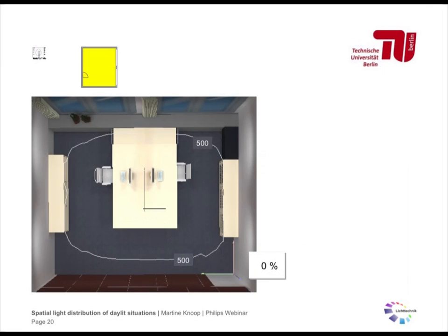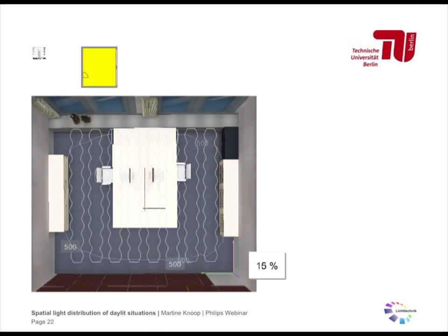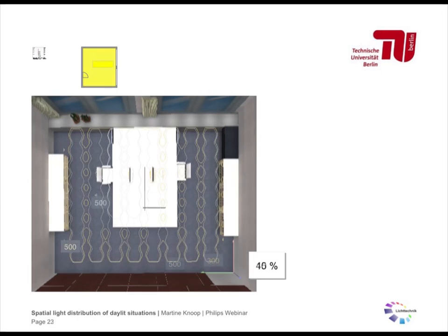Just to give you an impression about the energy savings, if I go back to the standard situation where I have 500 lux with a normal office luminaire and I realize 500 lux on average, I can of course reduce my energy consumption if I use directed LED lighting. Even if I still realize 500 lux on average on my work plane and keep the required uniformity,